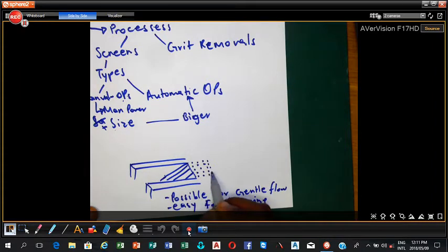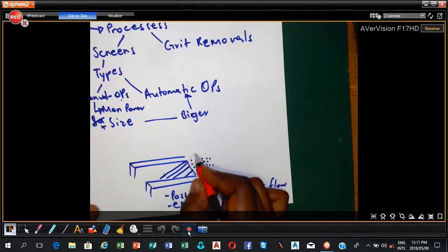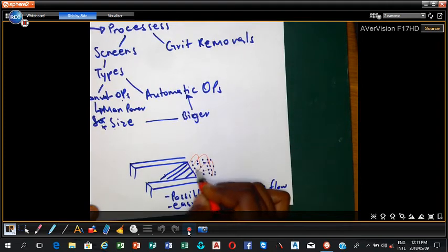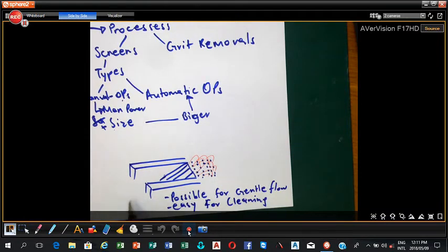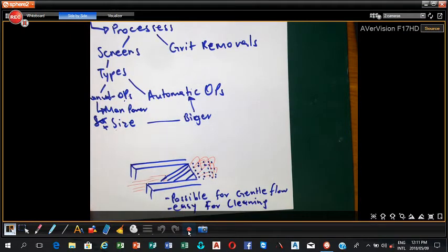Now, if the surface is perforated, it literally means that during the time you are cleaning your screens, you would put your screenings there. Why are you putting your screenings there after raking? Because your screenings are still wet, still combined with water, so the small perforated holes will then suck water back, and some of it broken down during the raking, back to the system.